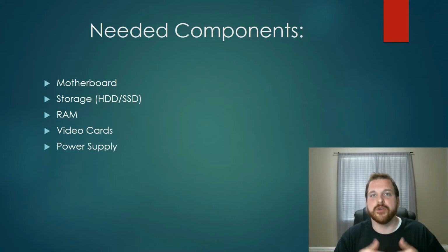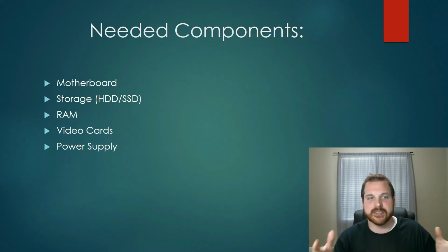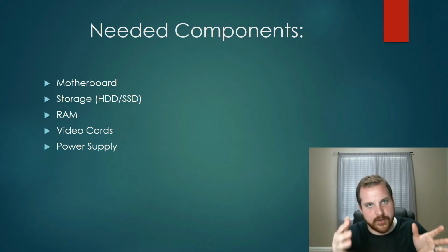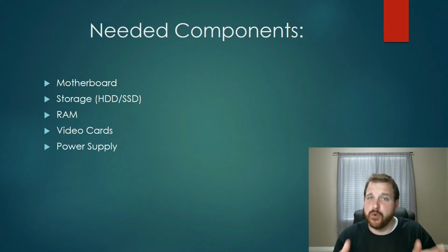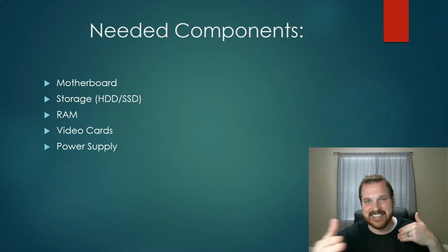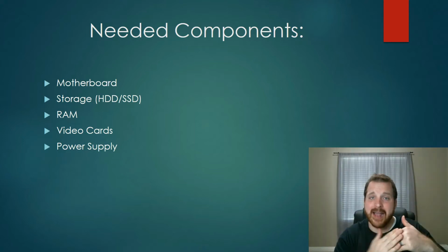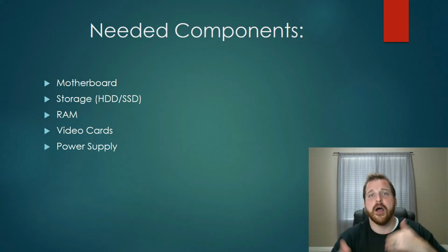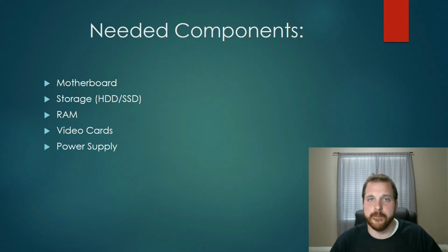So if you look at a rig and say, oh, this rig is gonna need 800 or 900 watts, you could get a 1,000 watt power supply. I may even ask you to consider a 1,200 watt power supply, just so that you're not getting close to that edge. Generally, when a power supply operates at 60 to 75% of max capacity is where it's most efficient. So once you get running in the 80 and 90% of its max capacity, it starts to pull more power, or use more watts than necessary, than it would at a lower wattage.